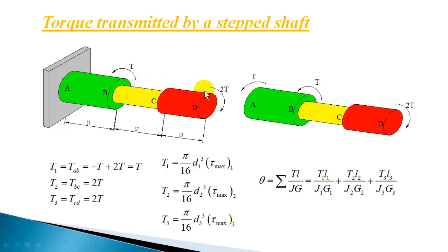on the shaft. Now here clockwise torque 2T is acting and here anti-clockwise torque T is acting. So the resultant torque, taking anti-clockwise as negative, is plus 2T minus T, you will have plus T, and that resultant torque transmitted to this fixed end will be clockwise, so plus T. So at the fixed end you will have a reaction torque which is in the counterclockwise direction.